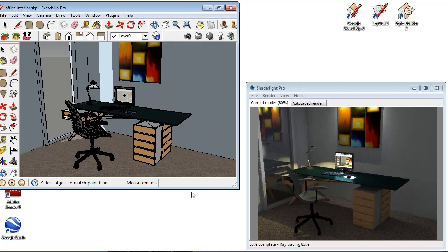For a tubular light, the best way to create it is, again, the self-illuminating material, and then draw an area light, a long, thin, rectangular area light in front of that tubular material. You can put those around one or two sides of that tube, and it will create the desired effect. We're always looking at the lighting options, to be able to create something like a neon light that emits light. That's somewhere we will be going in the future.